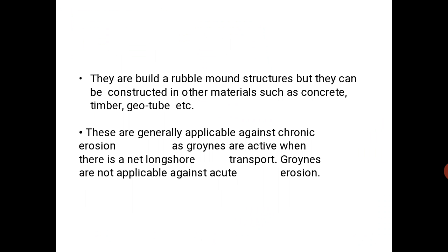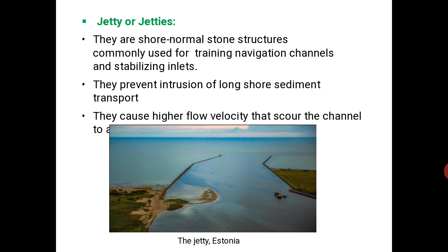Next one, jetties or jetty. They are shore normal stone structures commonly used for training navigation channels and establishing inlets. They prevent intrusion of longshore sediment transport. They cause higher flow velocity that keeps the channel open.